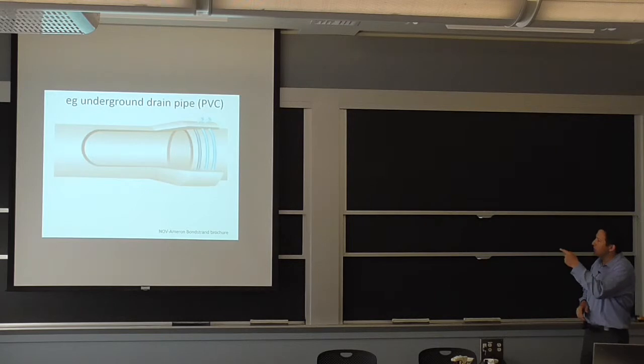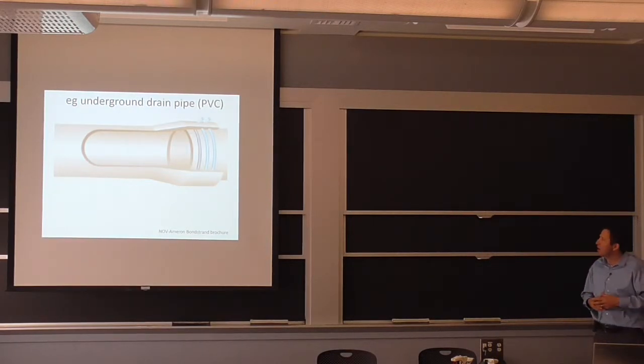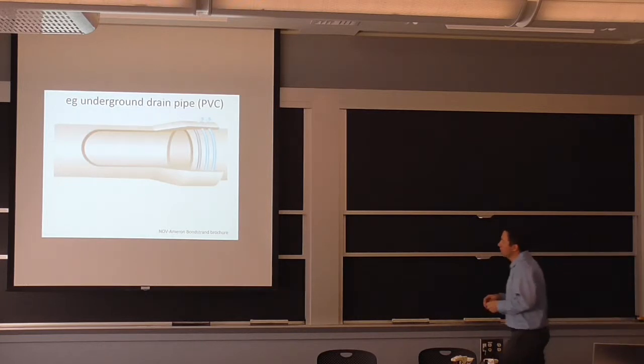And this is an example of a belled spigot. So you essentially have one pipe that comes in with O-rings and it gets into the bell and it forms the seal. A big advantage of a design like this, this can be up to 10, 12 inches or small, 2 inches inside. One advantage is you can have a little bit of expansion and contraction, so it's going to allow for slip here.